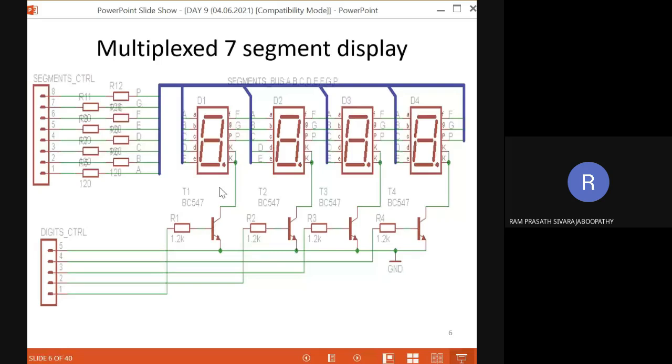Fine. We have to refer to the data sheet of the particular 7-segment LED. What about the turn on time? What about the response time of that particular LED? Approximately we can go for 1 millisecond to 10 milliseconds. Generally for key debouncing we use some timing. The same timing you can use here also. Is it clear now? That means the digit 1 appears for some time.